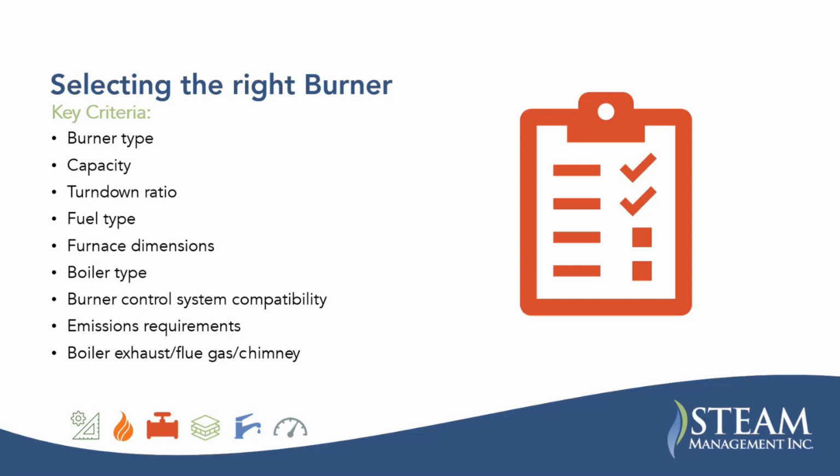Boiler type. Really, you can just give them the nameplate info on the boiler so they know what they're dealing with, which will also give them the furnace dimensions generally. And then what's the burner control system compatibility?